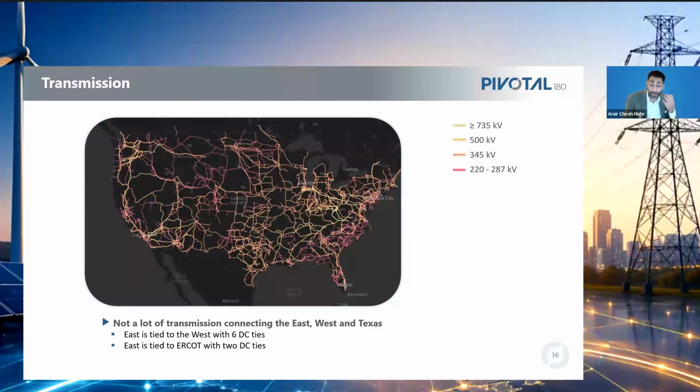That is why, unfortunately, when you see issues where, say, Texas has really bad storms and the electric power grid is affected, or there are times when there's enormously cheap electricity in West Texas because it's really windy, the prices even dip negative, and you would love to be able to export that power to other locations to generate profit rather than lose money in the system. But because you can only export between 2 to 4% of your power, or import that same 2 to 4%, each of these zones is independent, right? It's as if from an electricity perspective, the United States is 3 separate countries: the West Coast, the Texas region, and the East Coast. So at a 30,000-foot level, that's restricting the resources that we can channel from one place to the next.